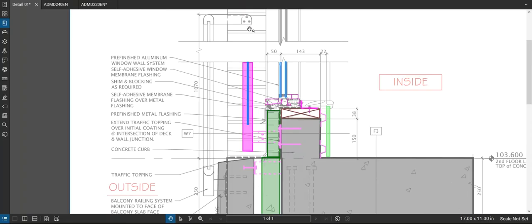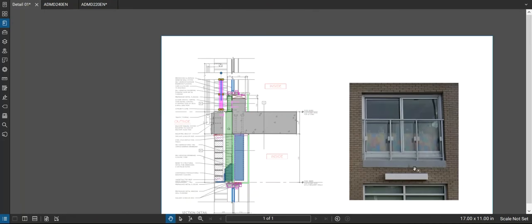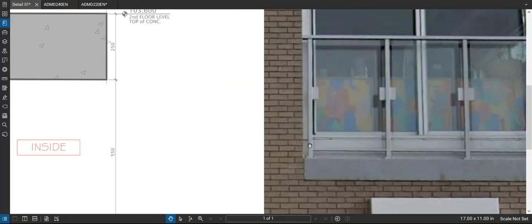And actually, I wasn't really happy with the idea of fastening this railing to the brick there either. So this helps, that the railing would extend up, but there's really no need to attach it on the sides. There'd be enough attachment just at each post. The end post basically here would have a knife plate going back to the curb there, and you wouldn't really need to. You could just stop that there.